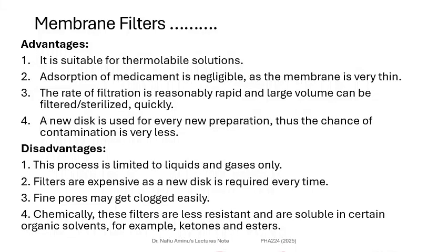Okay, sometimes we experience that problem, they clog. So when that happens, they have to be replaced. Then chemically, these filters are less resistant and are soluble in certain organic solvents, for example, ketones and esters, which means you cannot use them to process certain corrosive reagents.